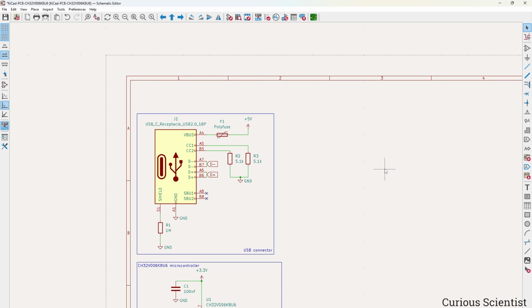And we can use a low dropout regulator instead of a DC-DC converter, because the voltage difference between 5 and 3.3 volts is very little, and we also don't consume that much power. So the heat dissipation through the chip will not be so high, so we don't have to worry about this part. It is a very low power circuit, and therefore we can use this regulator.